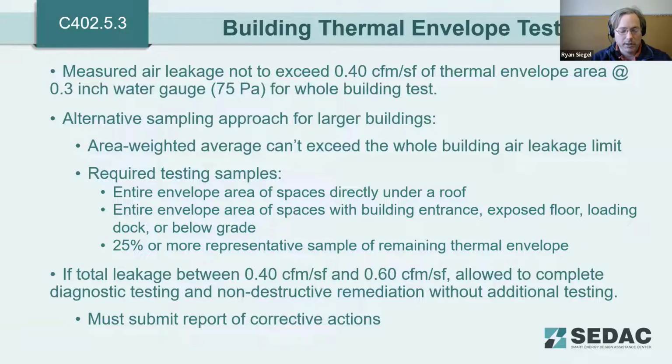Understanding that we're going to go through some struggles to begin with, the code does have a provision in here if you don't hit your 0.4 CFM, but you are not greater than 0.6 CFM during your testing, then you are allowed to pass if you go through and do your diagnostic testing, typically through smoke testing or some other diagnostic testing method. Ultrasonic might be another common method. And then non-destructive remediation and documenting all the corrective actions you took for that.